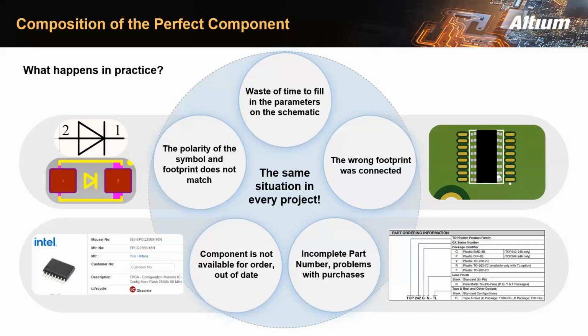late cycle at the assembly stage. Another common situation is that the designer uses a component from the library which has often been used before, but in fact the part is not recommended by the manufacturer for new designs. That is all. In the near future, its production will stop and it will be unavailable. Also, another common mistake is the name of the component, such as an IC missing the suffix code indicating the package type.